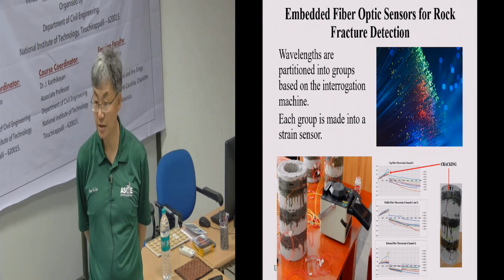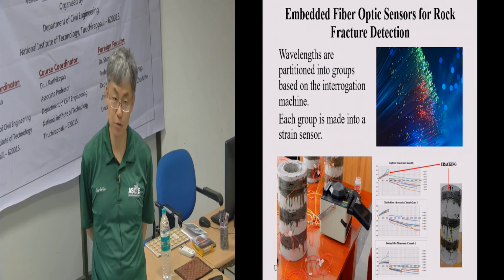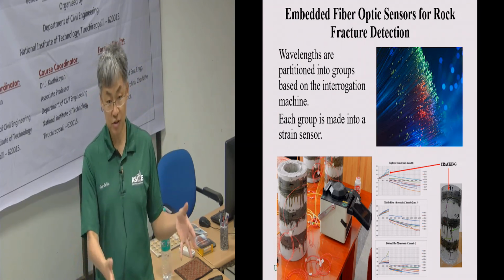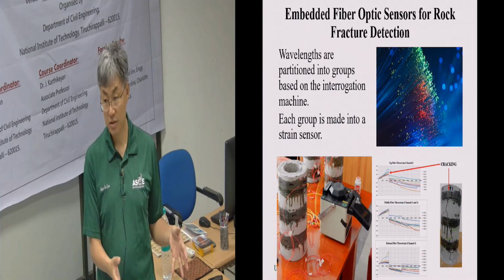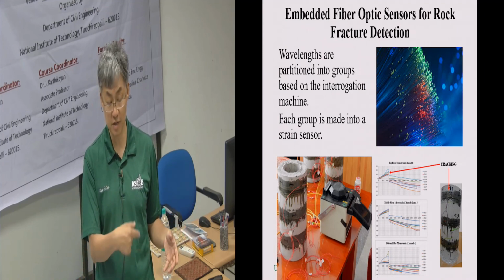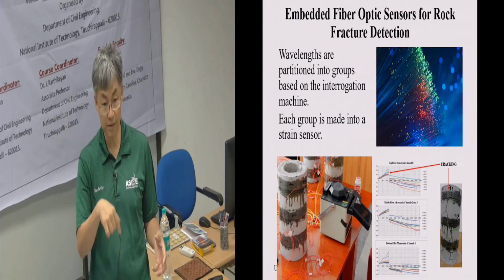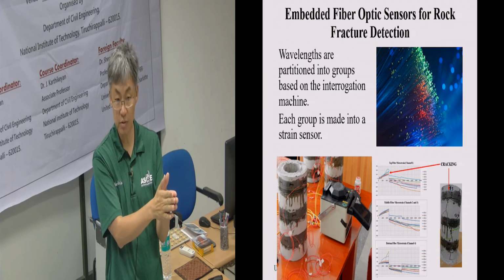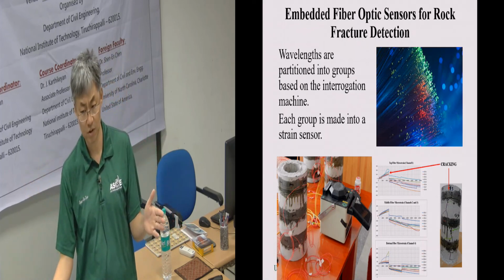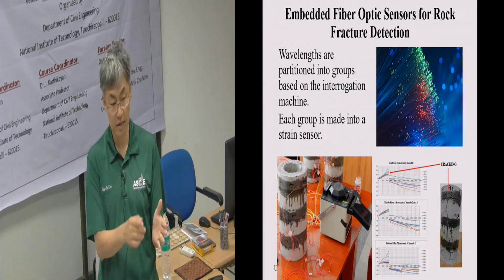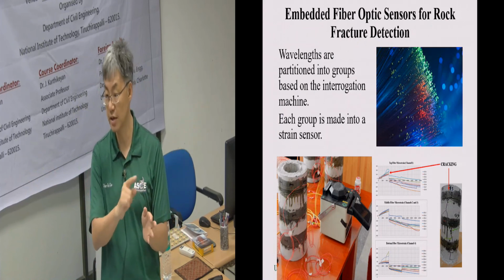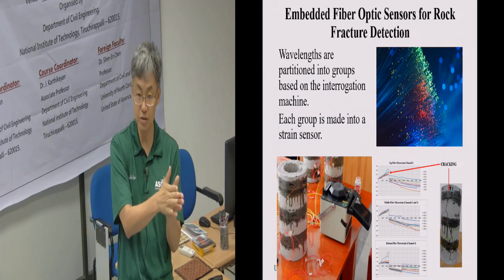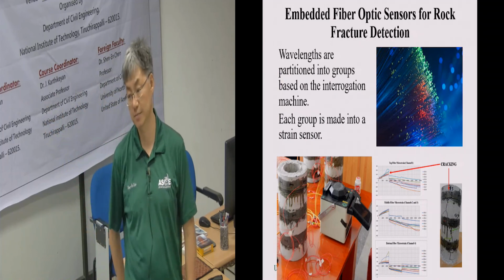But on the other hand, sometimes you can stress test, like a pressure tank leak problem. Sometimes we do what we call stress testing. So you reapply the force and then use the crack opening to determine what the condition was before. This is called the Kaiser effect. You can use this kind of gauge because you don't care about the absolute value, but you care more about the change in the crack during testing.